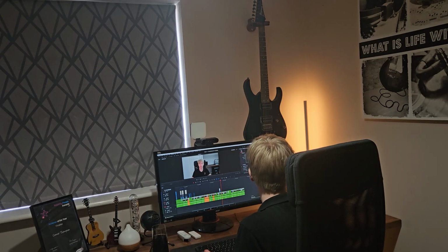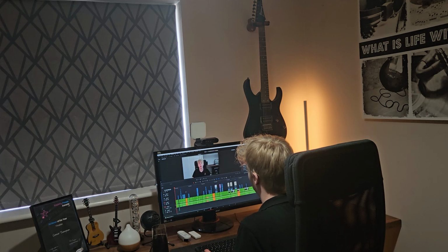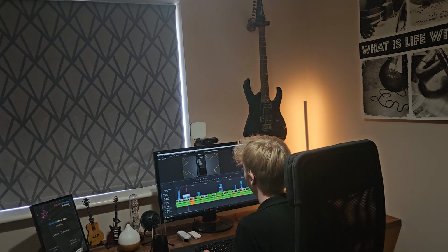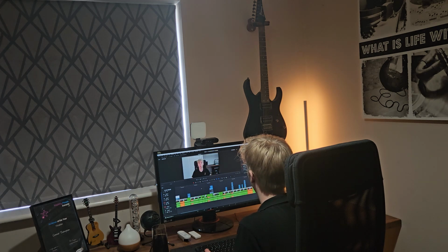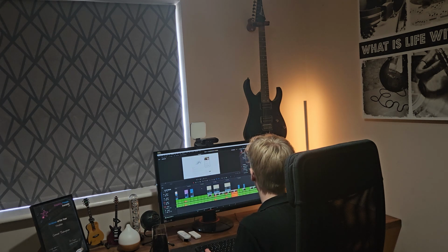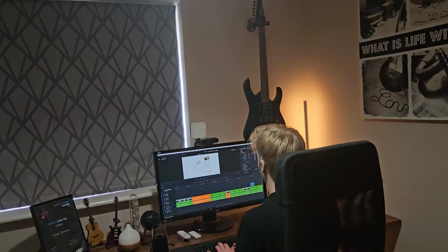So even in rooms like this office, when I'm sat at the desk, the light will never turn off on me because it knows that I'm here. Even if I am just sitting typing or doing very little movement, it knows that I'm here. Whereas a PIR sensor or a motion sensor would fail to detect me after a prolonged period of time of me sitting at this desk, and it would end up turning the light off on me.